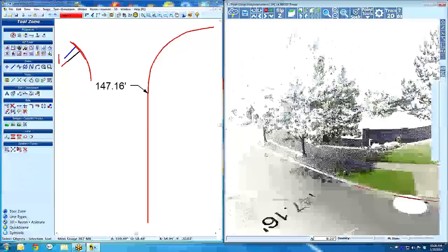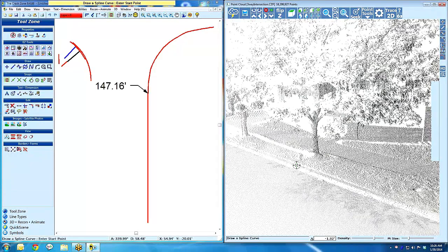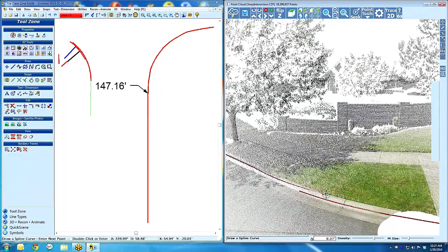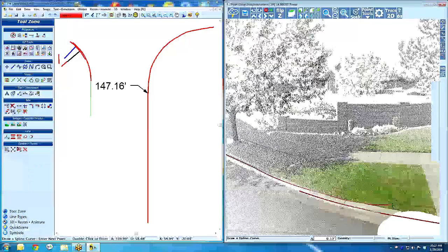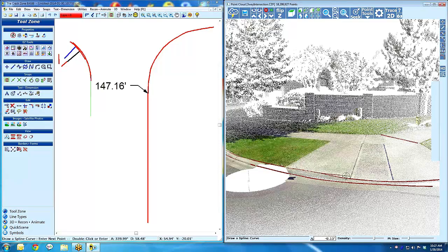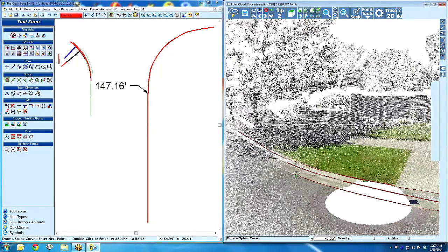And just a little quick note, if you were zoomed in, like say right here, and you were clicking to draw, and you don't have enough screen, but you want to keep drawing, well, you can't click your mouse to navigate now because you're in the middle of drawing. If you hold down your Control key, then you can now navigate. You can pan and then start clicking again. You can hold down the Control key and rotate, move around. So the Control key just gives you access to moving around in here, and then I'll hold down the Control key again. I could just use my mouse to navigate again without slowing me down.